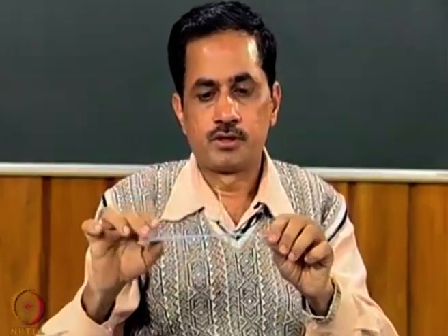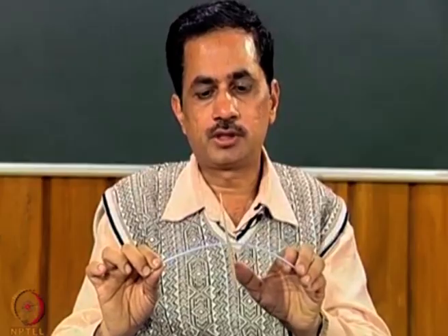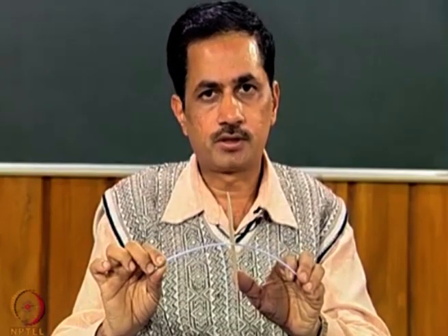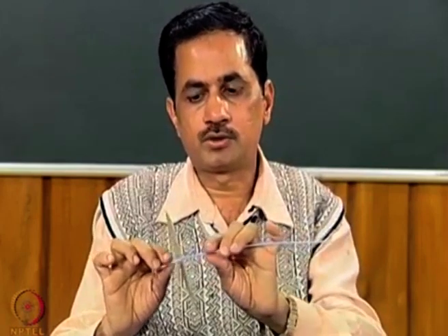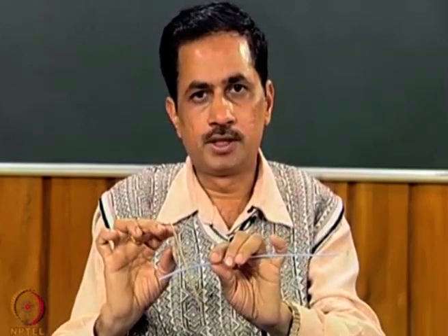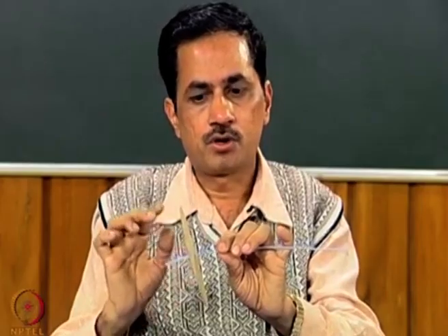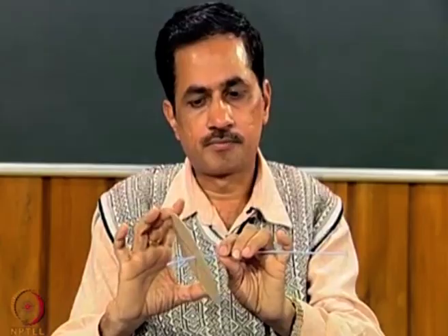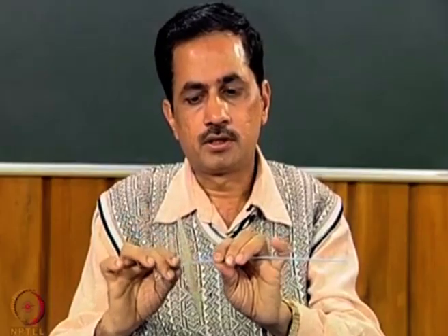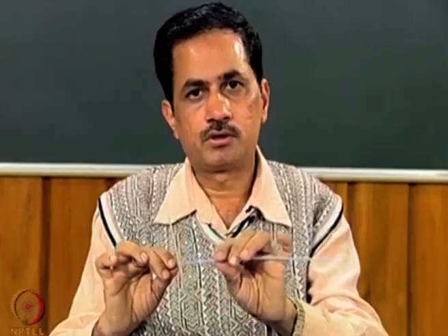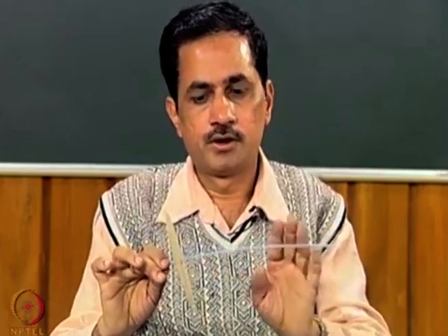In the previous case, when we considered the disc at the middle, we could define the position of the disc by just its x and y position. There is a translational motion, but when it is at the offset position, we now need to define the orientation of the disc also, because of its wobbling. So not only do we need to define the two translational displacements x and y, we also need to define the tilting of the disc about two axes, the x and y axis. So here we will have 4 degrees of freedom, or 4 variables, to define the position of the disc. And this is the variant of the Jeffcott rotor in which the disk is offset from the center.